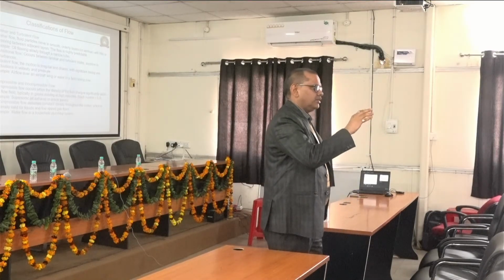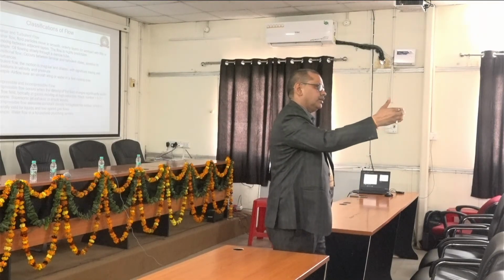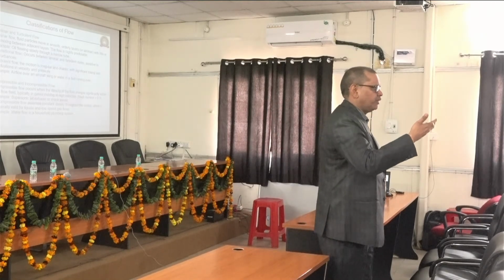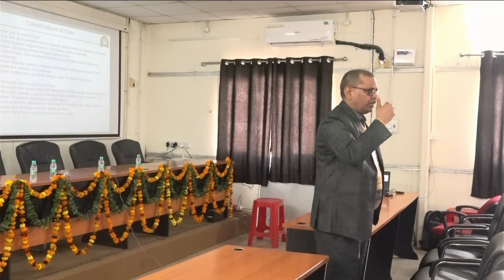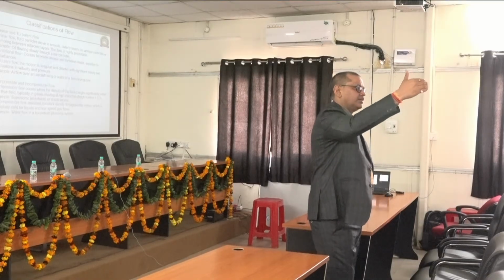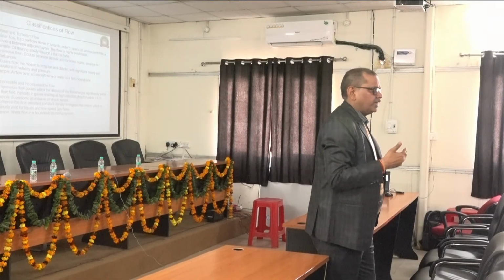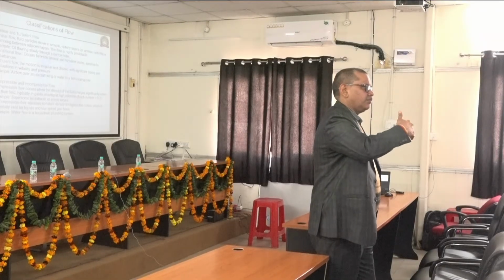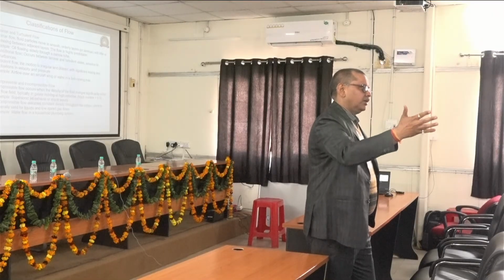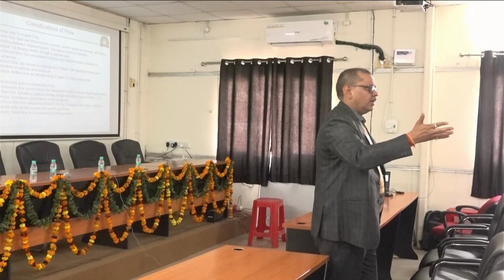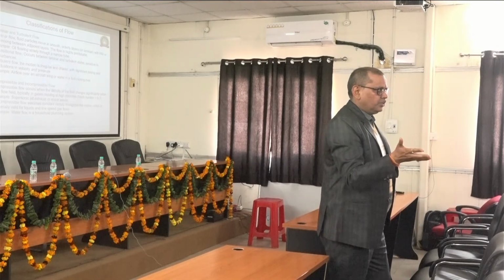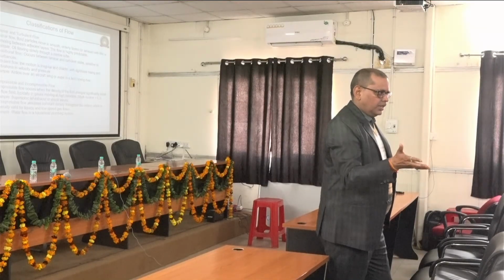So pattern means if there is a flow of the fluid particle, because fluid is constituted from different molecules, fluid molecules or fluid particles. So there is a path of the fluid particle. That path you can consider in flow or fluid dynamics as streamlines. If the pattern of the streamlines is parallel and very smooth, if they are not zigzag in nature, or not intersecting each other, then it is uniform, or laminar in nature.